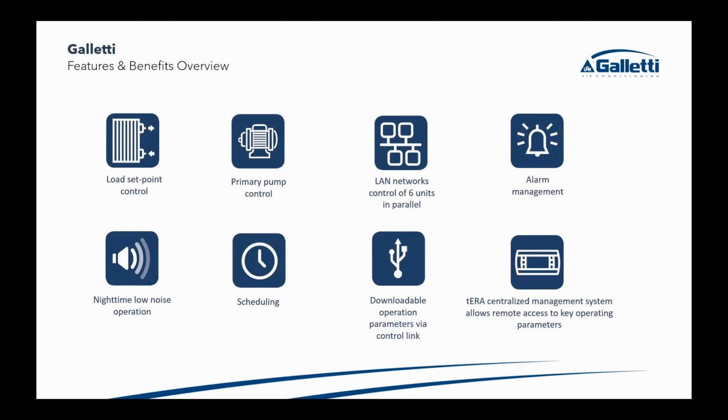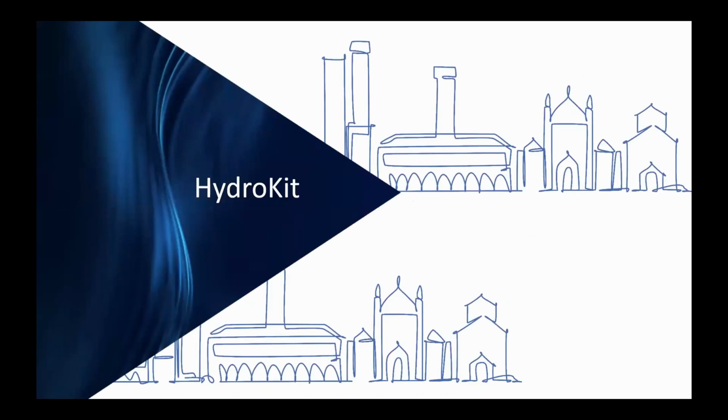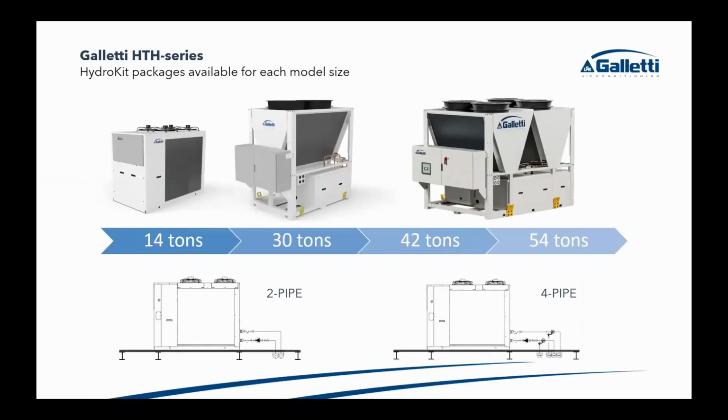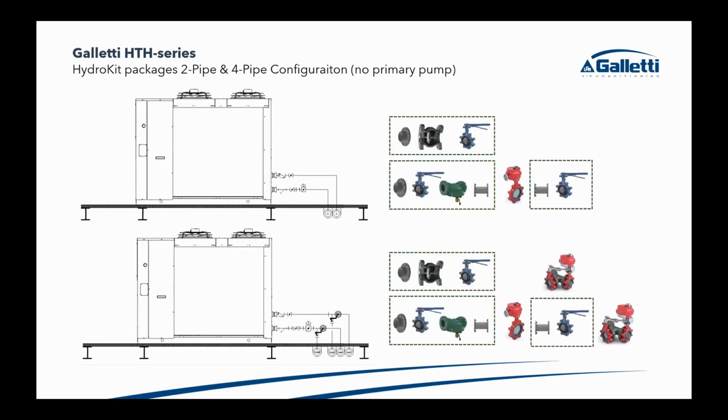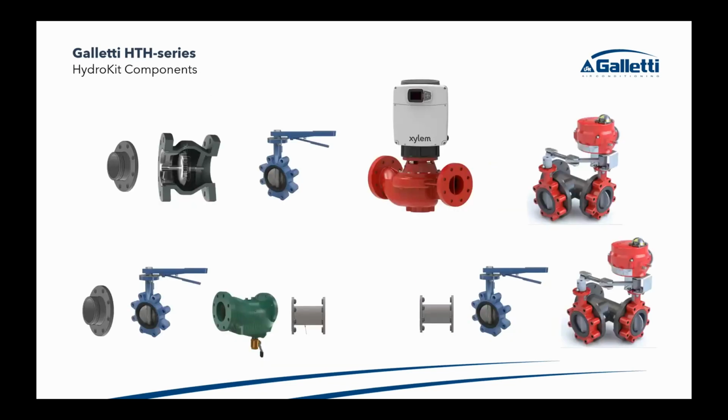The units all have their onboard controllers, and in this case, these units would control six based off their onboard control, and after that, every six would be grouped together. But I think that's pretty standard. In this case, I just wanted to show that, just like boilers and everything out there, there are packages for the near-boiler piping. In this case, the near heat pump piping, where you can select 2-pipe or 4-pipe systems and get these assemblies. I just wanted to throw in a picture of that. It includes the pump, and the pump is the E80X.